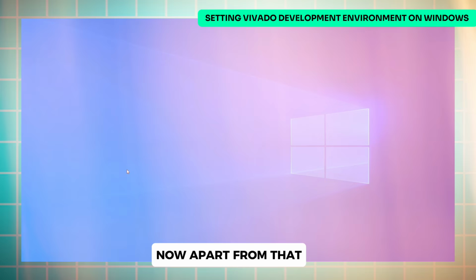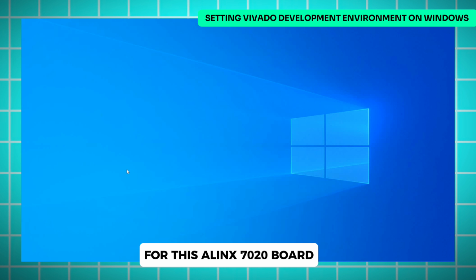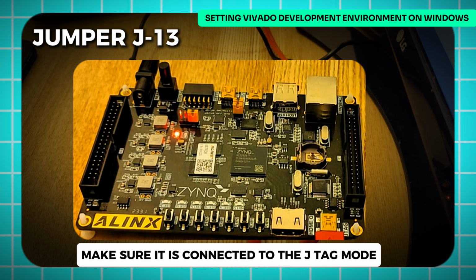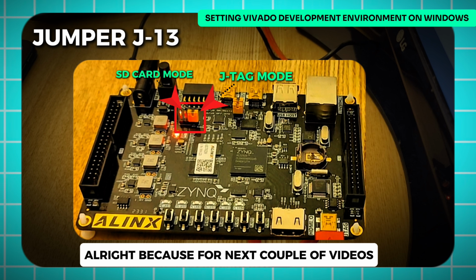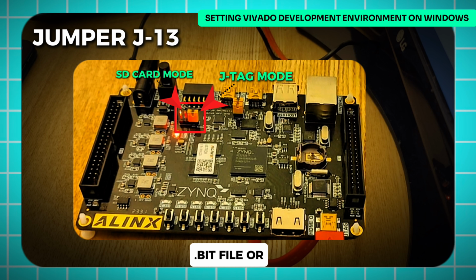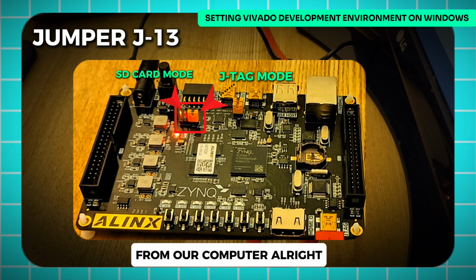Now apart from that, I just want to highlight one more jumper configuration for this ALINX 7020 board. And here we have this jumper J13. Make sure it is connected to the JTAG mode, not the SD card boot mode. Alright, because for the next couple of videos we are just going to flash the .bit file or bitstream file directly into the development board from our computer.